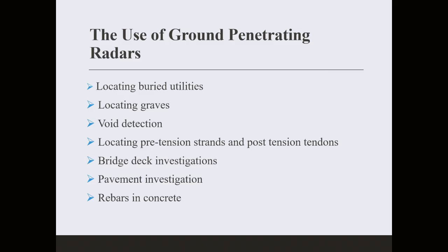So this one is used extensively on top of any asphalt. It can tell you the thickness of the layers. It can tell you the quality of the layers, the possible presence of deformation. It can be used even for utilities if you are trying to investigate the presence of utility pipelines, electrical cable before doing excavation, so you don't hit anything. The GPRs can easily tell you this.